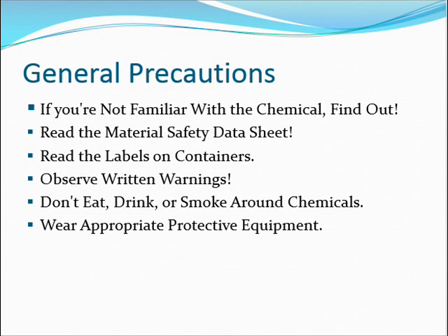General precautions. If you're not familiar with the chemical, find out. Read the material safety data sheet. Read the labels on containers. Observe written warnings. Do not eat, drink, or smoke around chemicals, and wear appropriate PPE.